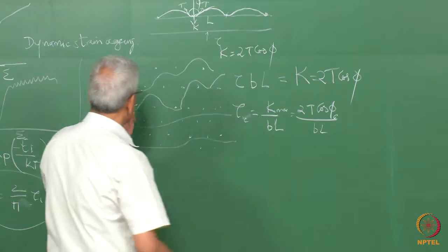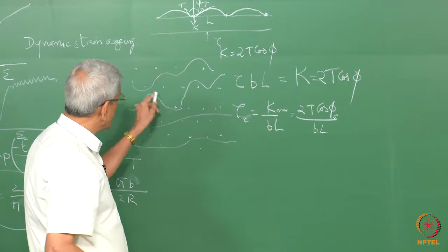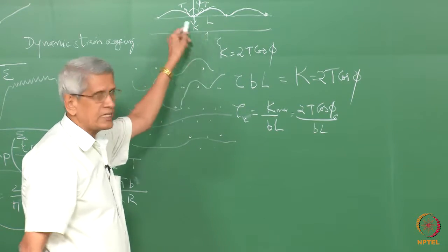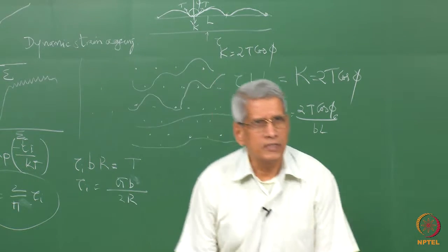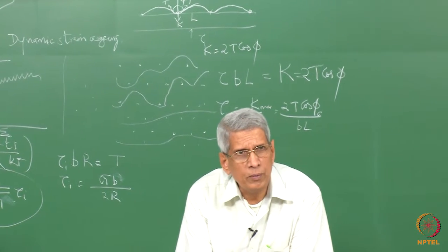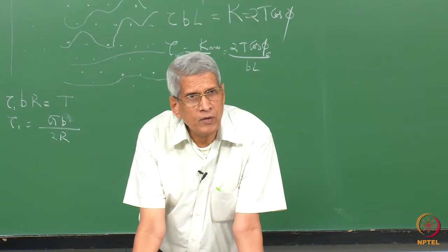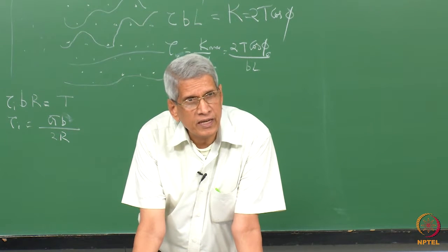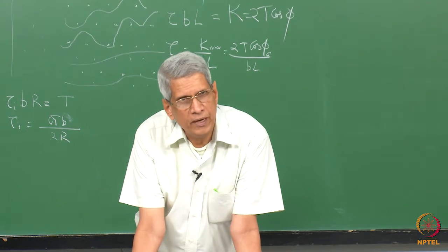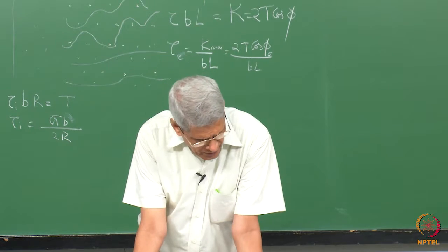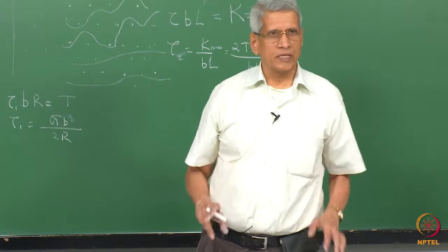If the dislocation line is a straight line, then we can calculate and say that the line spacing is equal to 1 by root n. But that will not be possible when the dislocation line is not a straight line. That means some statistical averaging has to be done. That statistical averaging is called the Friedel spacing.